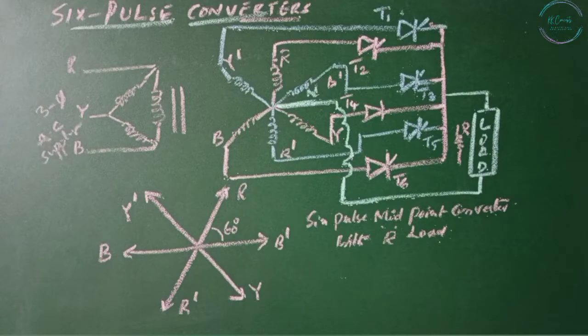6 pulse converters are popular because 3 pulse converters require a special type of conversion transformer. The conversion transformer is used to prevent demagnetization for large outputs and least ripple content. A 3-phase controlled rectifier with higher pulse number is used. Generally, for industrial application, 6 pulse and 12 pulse converters have been used.